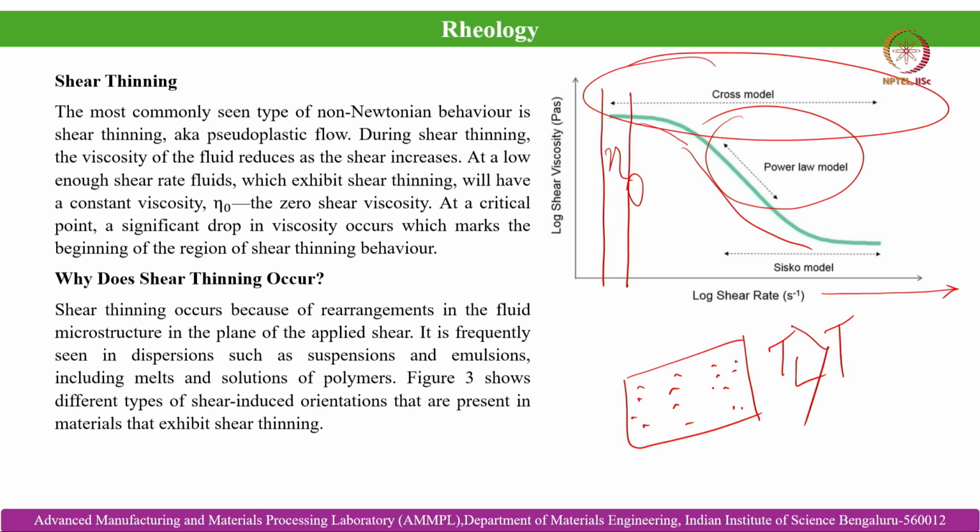In those situations, as we have discussed earlier about the nucleation mechanism of the primary solid grains from the liquid melt, these primary solids emerge, and then when we apply the shear rate, it allows these particles and also the fluid to glide past each other in a smoother manner.